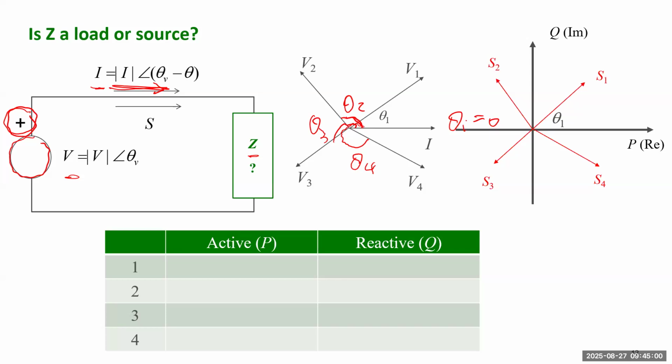If you visualize the calculated complex power in all the 4 quadrants, based on the sign, you will know it's a load or source in terms of active or reactive power. Because the impedance triangle is similar to the complex power triangle, we know also that Z1, Z2, Z3 are also in that direction. So it's up to you, when you have such a problem, to figure out the real role of some device.